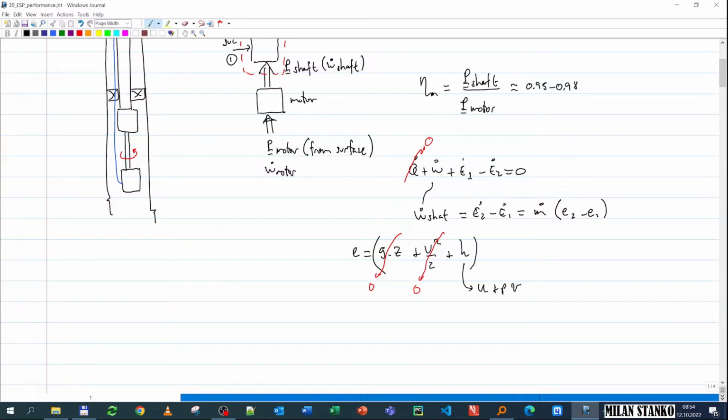So if I consider an ideal pumping process, that means that I have no irreversibility, no non-idealities, I have no friction, I have the process, it can be reversible, then in that case I might say that the process is isentropic, which is delta S is equal to 0. That's the ideal pumping process. That means that that's the one that will require the smallest amount of work.